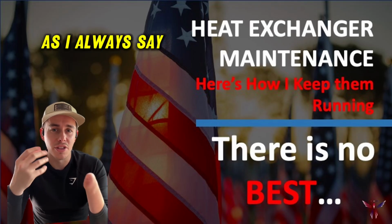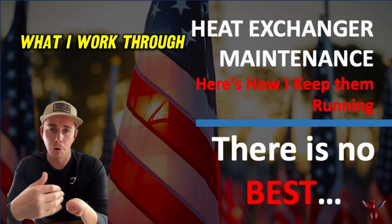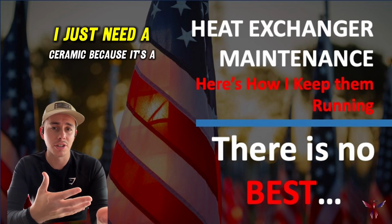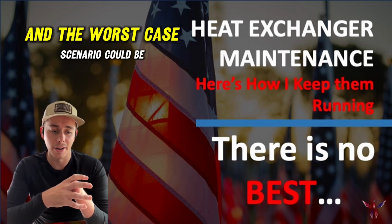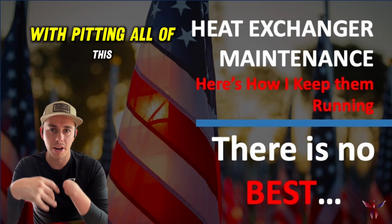As I always say, there really is no best for these systems. The steps that I gave you is what I work through in deciding what we're ultimately going to apply. In some cases, hey, the best might be I just need a ceramic because it's a brand new system, but the previous one had fouling and we just want to protect it. And the worst case scenario could be it's a 10-year-old system with fouling, with corrosion, with pitting, all of this.